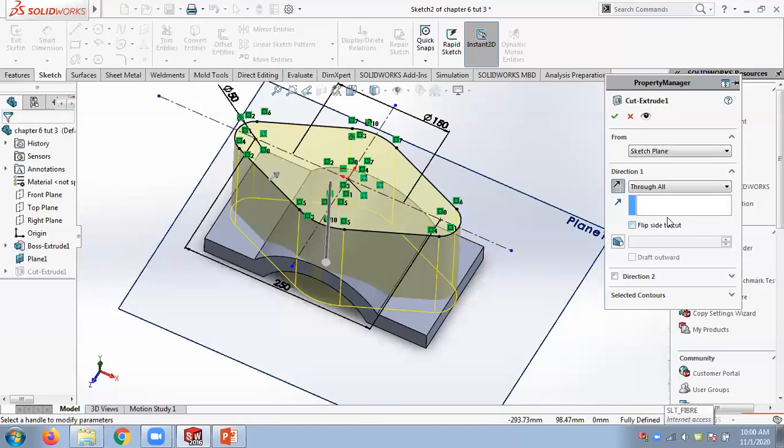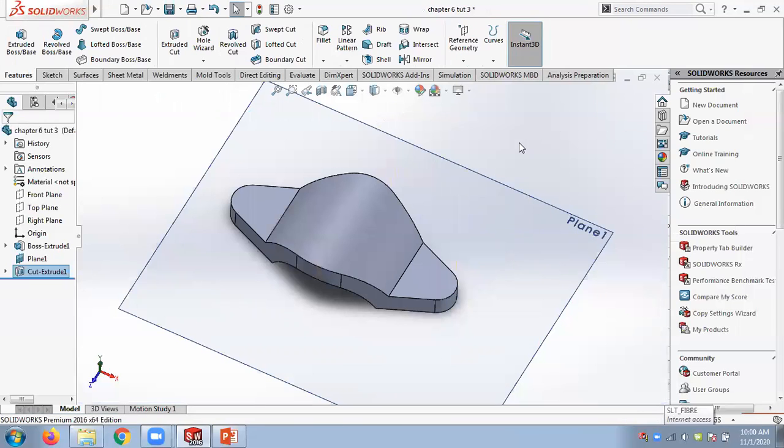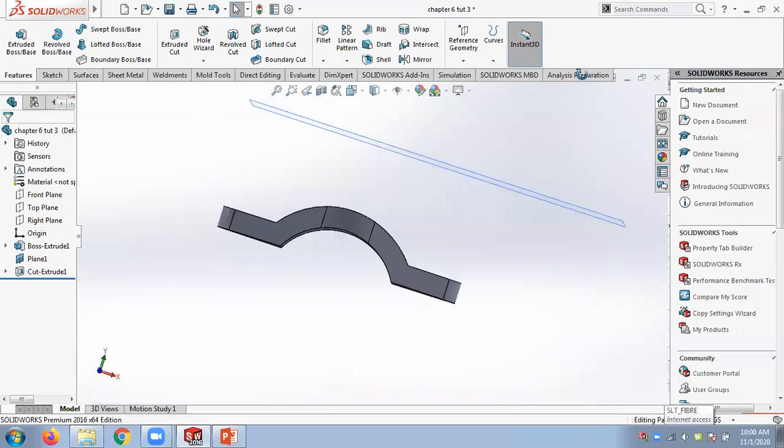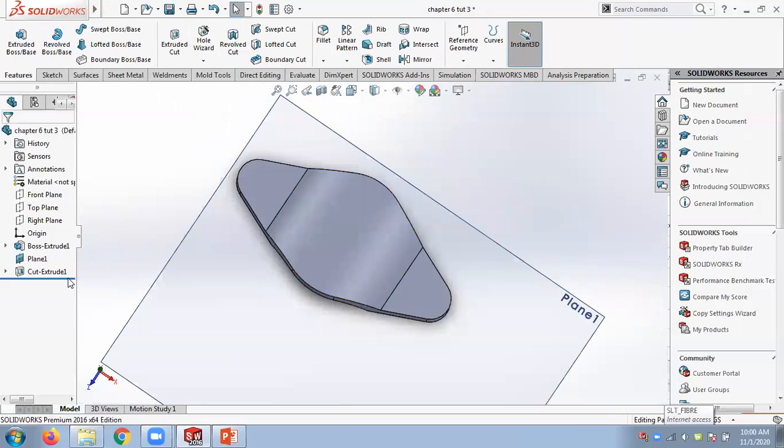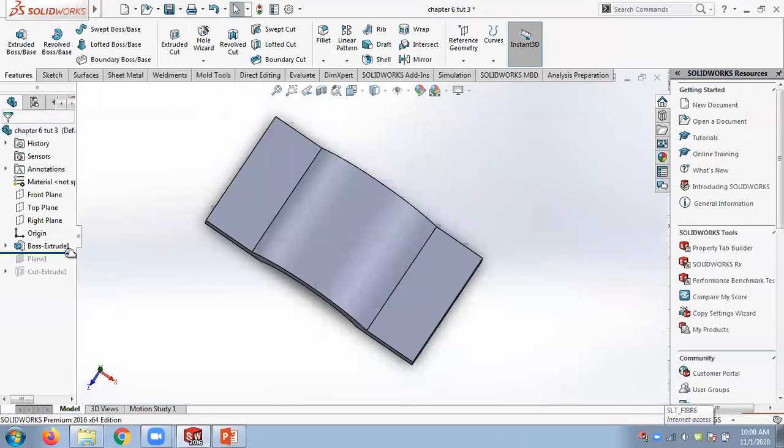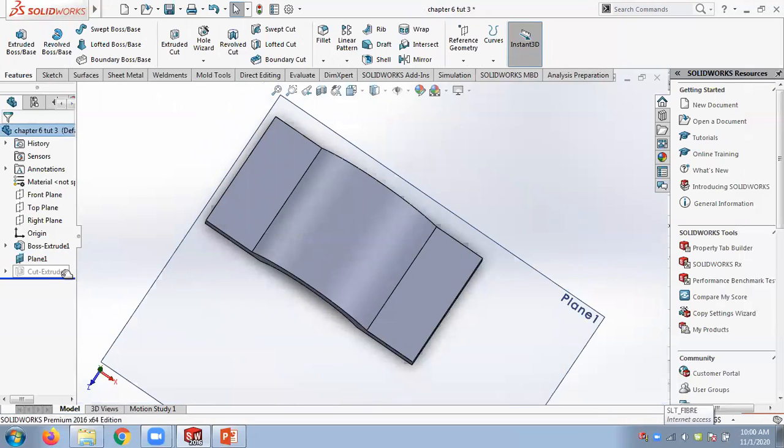I didn't teach this one when I taught the tool earlier. So there's a tool available to select the cut-in area. I have to remove the outside material, so just select that one and remove the outside material. So this is the shape I am getting. I hope you understood. If I reverse my operations, you can always reverse this. This was the starting; then I created a plane and I cut this way.